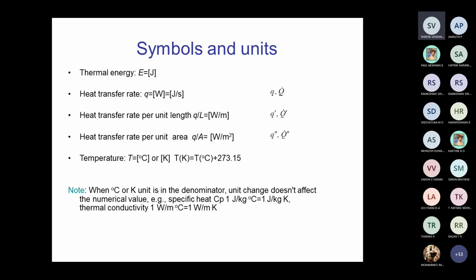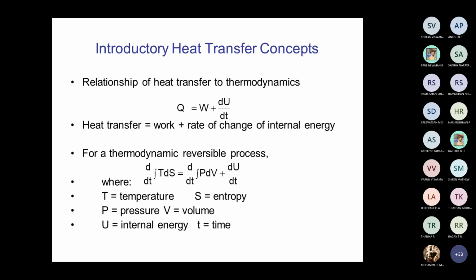Similarly, thermal conductivity 1 watt per meter Kelvin is equal to 1 watt per meter degree C. This is very, very important, and some of the students used to make a mistake here. Please don't do that. And these are some of the relations.